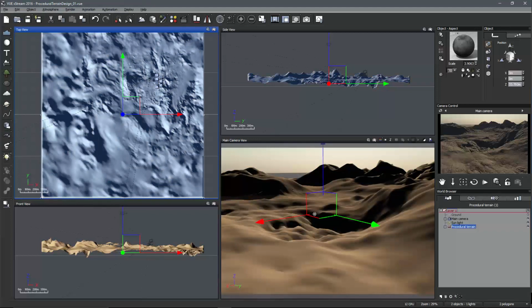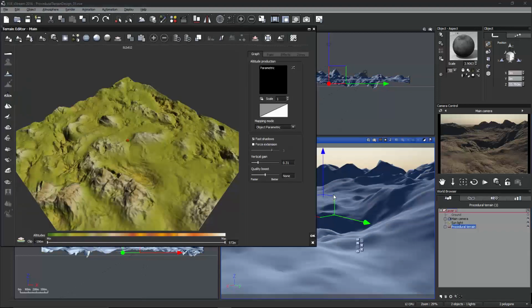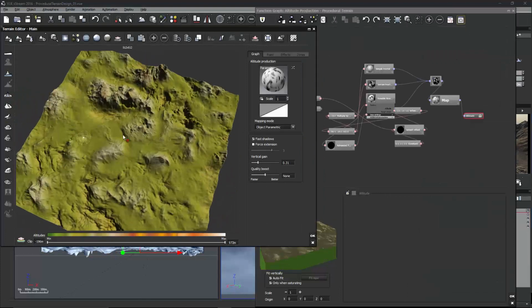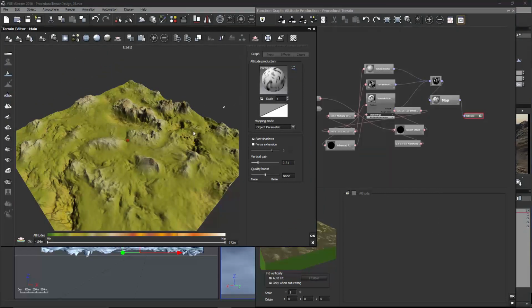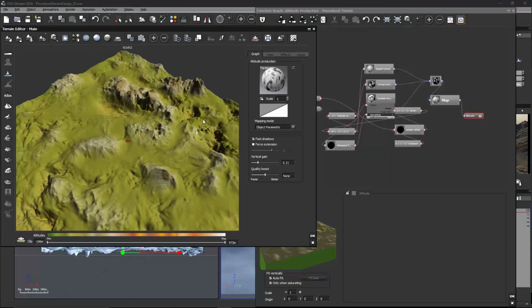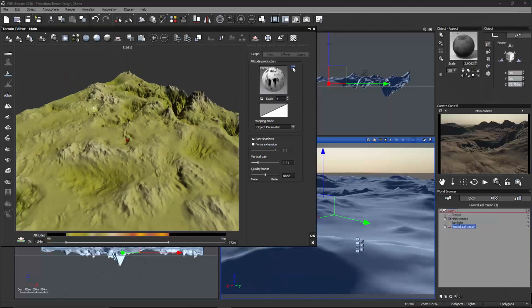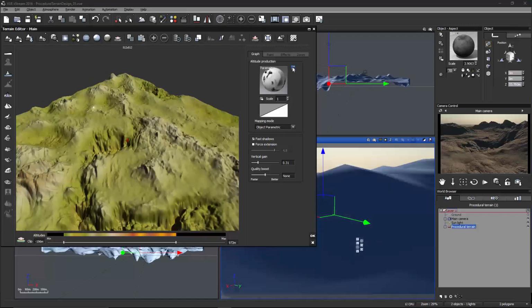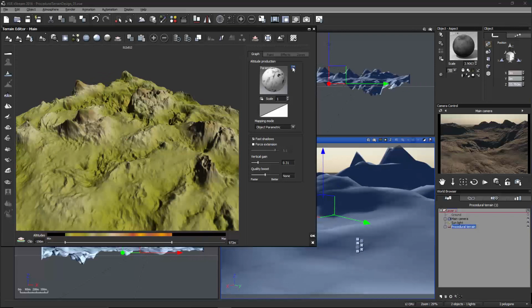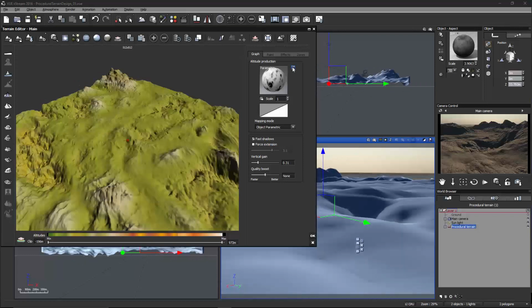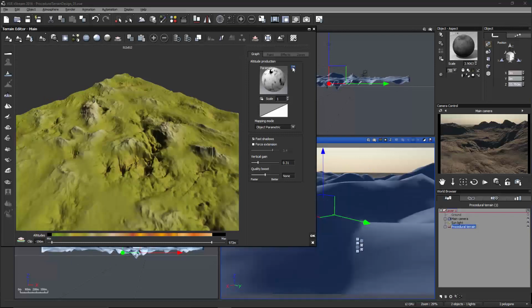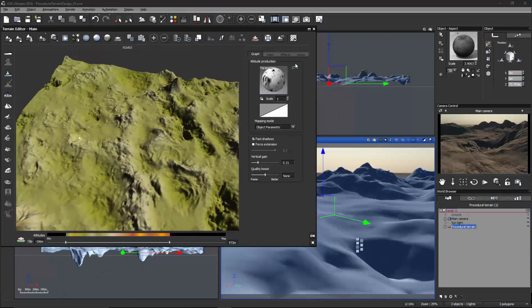So if we go back into the terrain editor, we also now basically have kind of like a terrain preset we could load in for this design and style of terrain. But if this isn't the exact shape we're looking for, not the right features, what we can do is just randomize it, and then we can move around the vector to get something closer to what we're looking for. So we can use that existing fractal and just move around within it. You could go in and change the vector manually too. But this way it gives us some nice random numbers in order to generate different terrains.